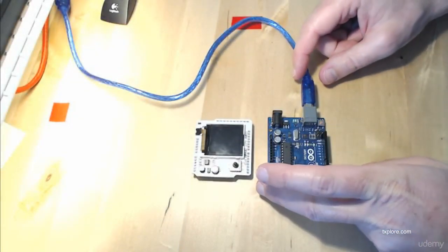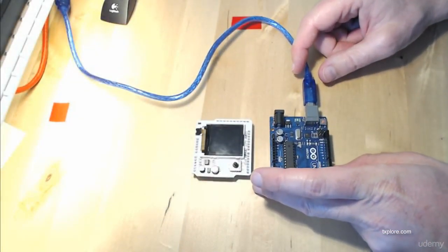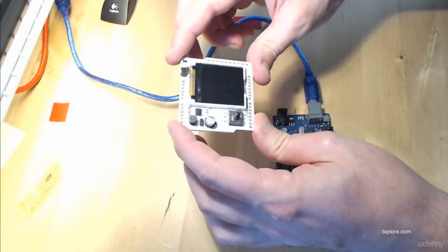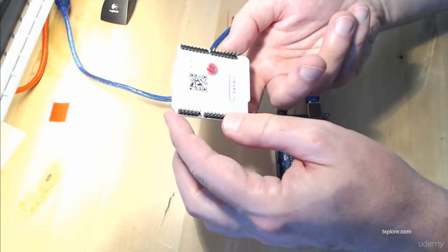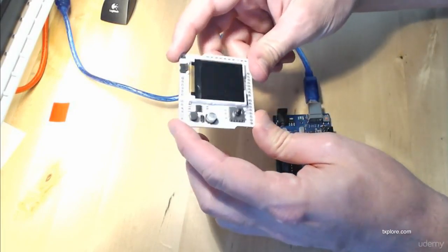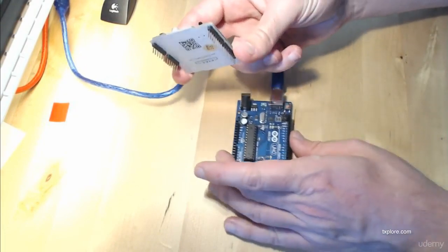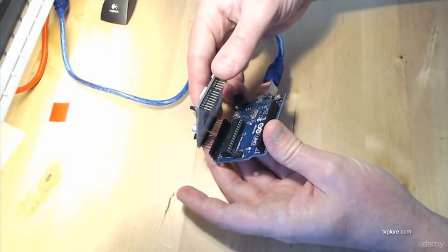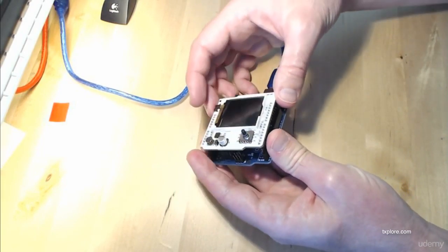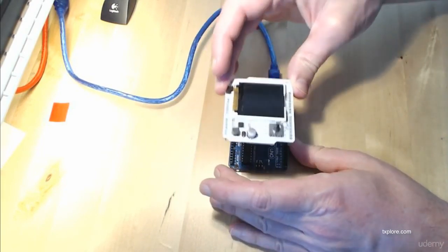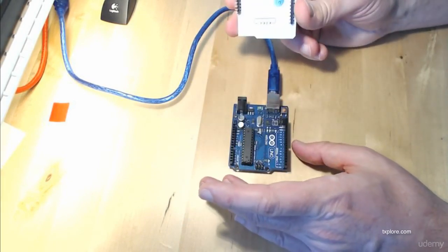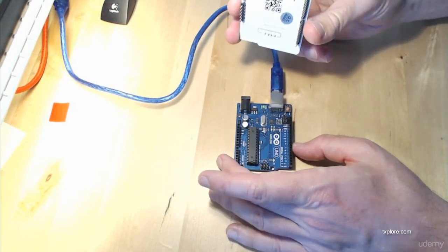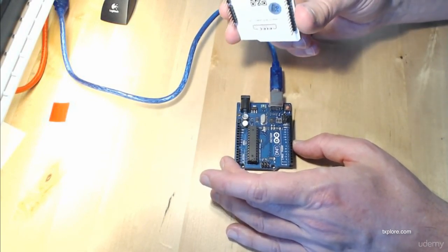I'm now going to show you how to connect a TFT LCD screen to your Arduino using this TFT screen shield. It's the first shield I'm covering in this course. So this is what shields look like. Essentially, they are a printed circuit board that matches the layout of the pins on the Arduino, in this case the Arduino Uno. You can plug it on top of it. There's no wiring that you need to do. There's no breadboards. It's just very simple plug and almost play.